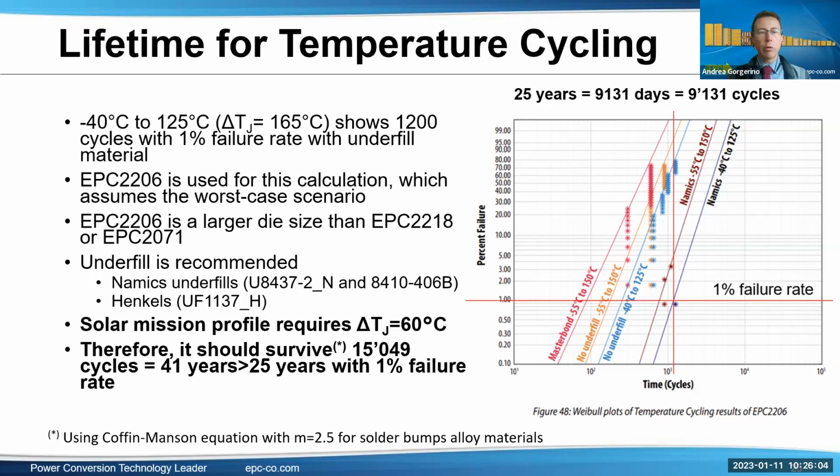So as I mentioned, we do recommend underfill. These are the two that we tested that provide good performance. They're shown in the chart. You have to pay attention to how to pick the underfill. There's quite a few interesting observations and test results in the reliability report. I suggest you take a look at that.